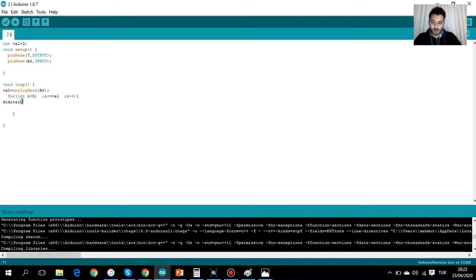It means digital write. I'm going to write it down. Digital write 7 is going to be high. Yeah, that's the point, guys. And here I will put the delay to understand whether time is passing or not. Close it. What does our code here mean exactly, guys?